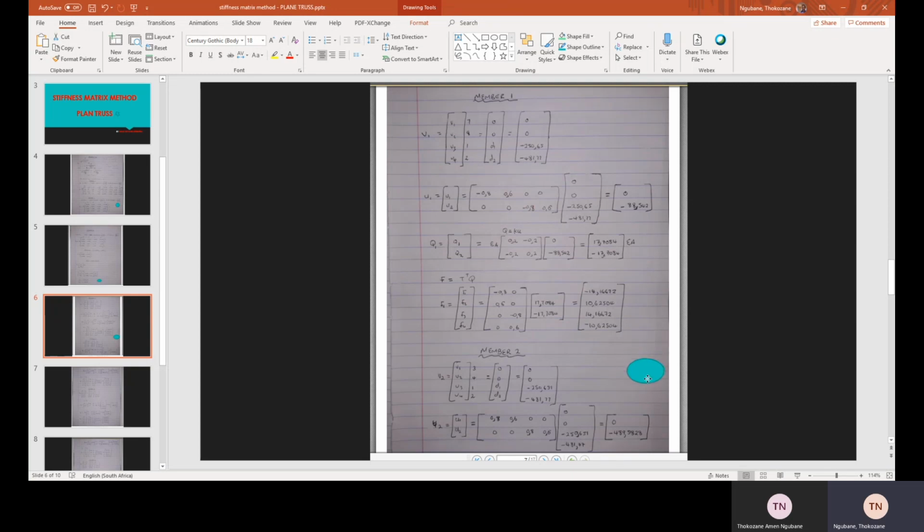Okay, let's continue. It's gonna be the same procedure, guys. It's easy. If you understand what we did on member 1, we're gonna do the same thing on member 2. We're gonna find V. We name our nodes 3, 4, 1 and 2. You don't have force on 3, it is 0. You don't have a force on 4, it is 0. Then on 1 we have force T1, and on 2 we have a force T2. Then we take those values of T1 that we calculated previously, that's why we have them here.